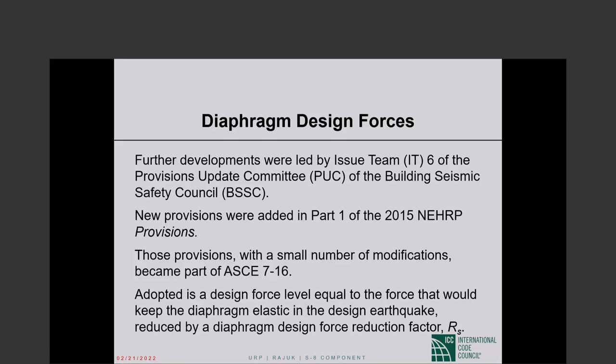Okay, doctors. To design a diaphragm, you mentioned only shear walls, but for columns, do the design procedures differ, or is it the same? It's just a diaphragm typically sitting on columns. It will sit on frames. Okay, and the shear transfer will be the same. It will go to the beams of the frame.